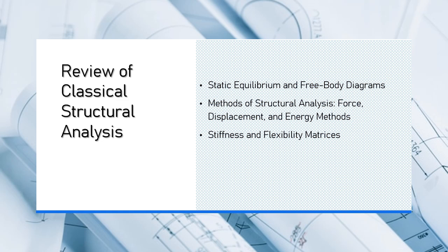2.3. Solving for unknowns using static equilibrium. Once the free body diagram is complete, we can use the static equilibrium equations to solve for unknown forces or moments. For example, force equilibrium. Solve for unknown forces by applying the force equilibrium equations ΣFx = 0 and ΣFy = 0.